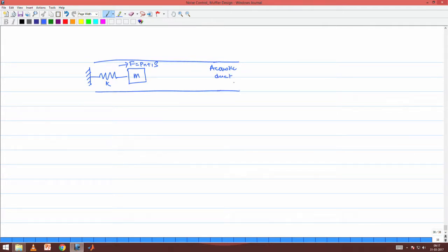that means there is an acoustic wave which is set up to the right side of this mass. That is pretty clear, right. To the right side of the mass there is an acoustic pressure field which exists. Now, that acoustic pressure field multiplied by the area is going to be the force which is acting on the right face of this mass.